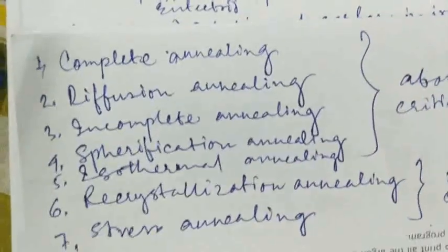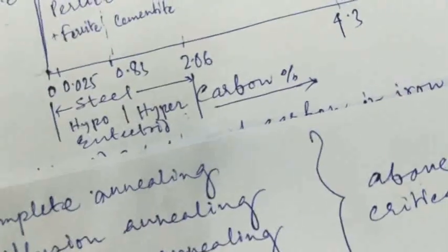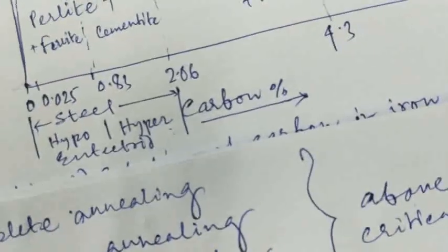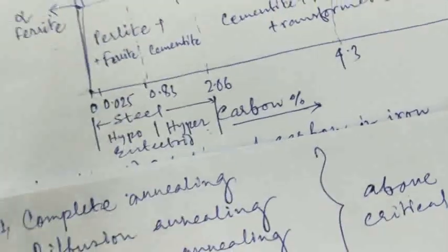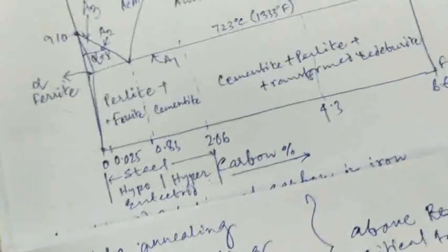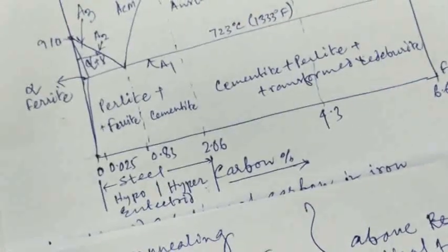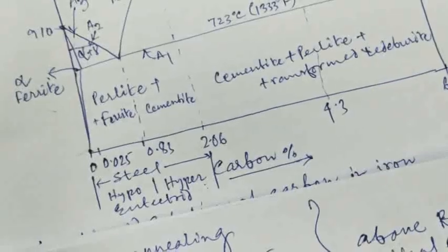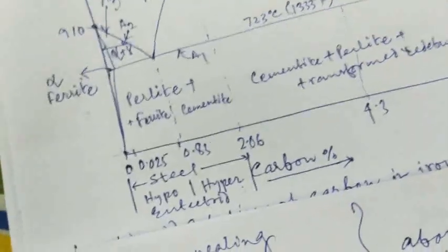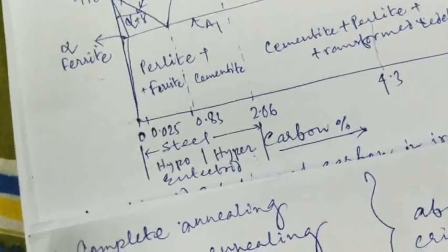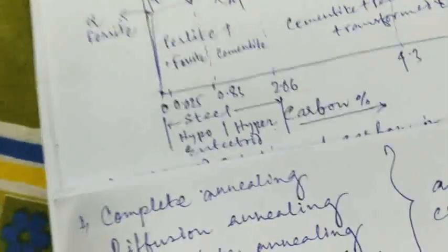Our next is recrystallization annealing, also known as intermediate annealing. It heats the deformed metal to the recrystallization temperature and maintains it for the appropriate time so that the deformed grains change into uniform equiaxed grains, eliminating work hardening and residual stress.